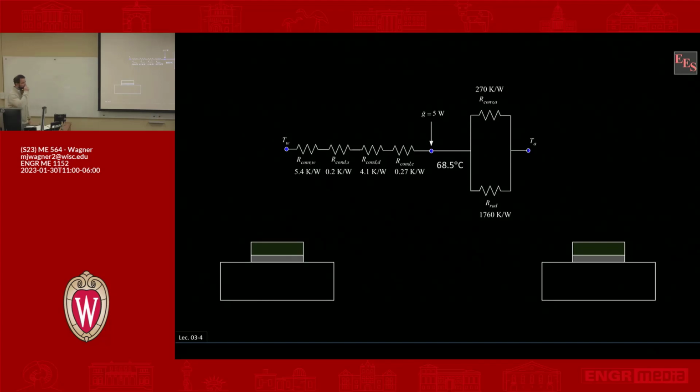Again, in this example, one assumption that we made, which is an important assumption, is that the area available for conduction in the spreader is this full width. But in reality, if you're a little unit of heat moving through this device, let's say you're over here on the corner, and this whole thing is at the chip or the dielectric temperature. This whole thing is at the spreader.